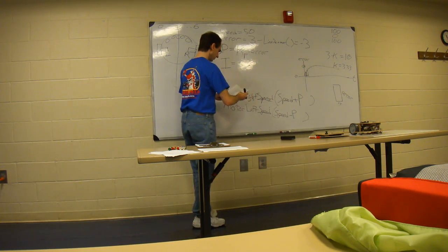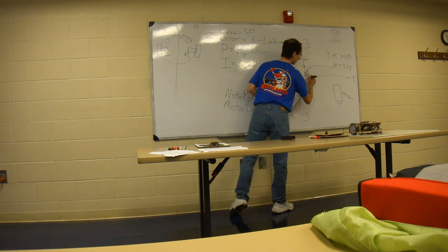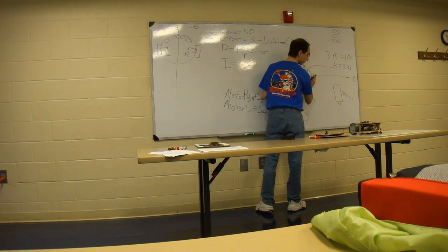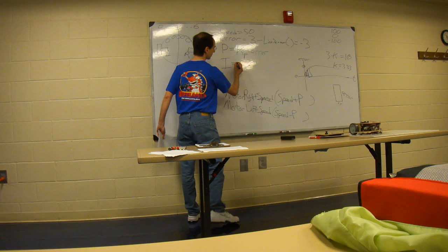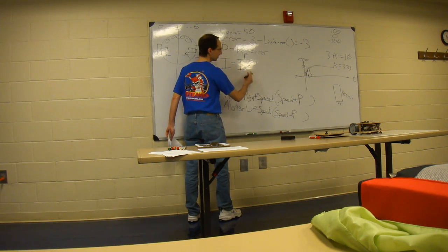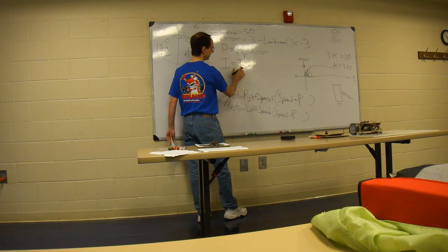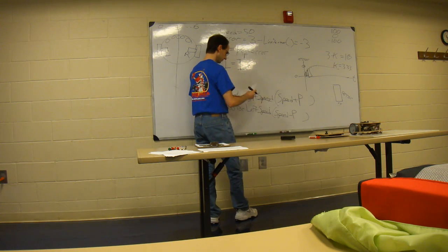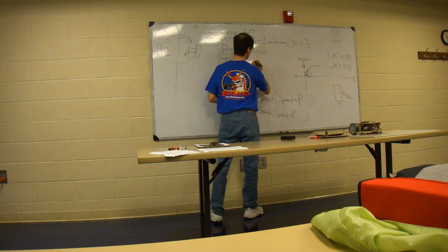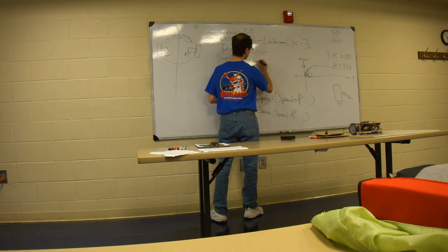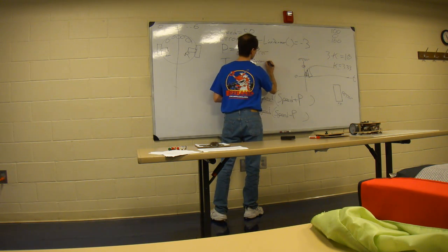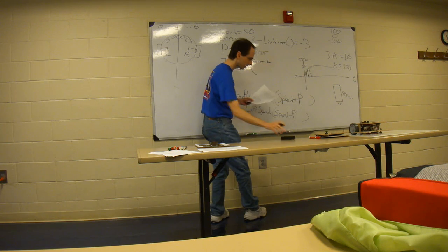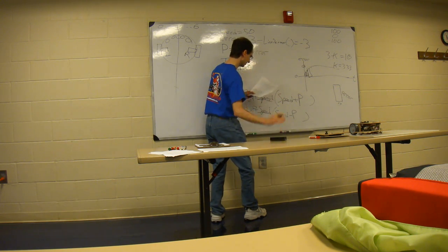So for each loop, we want to add them all up. We want the entire area, not just each individual area. So we're going to accumulate all of those little rectangles into I. We're going to say I equals I plus each of those little areas: the error times the loop time.